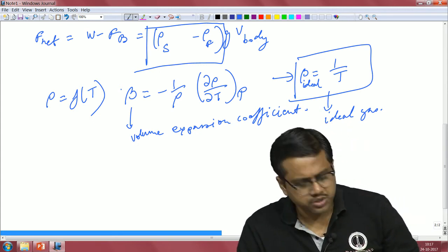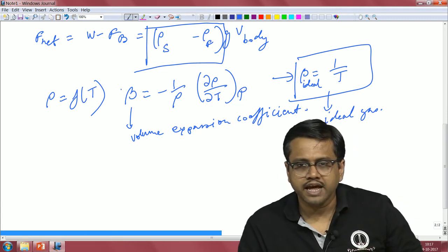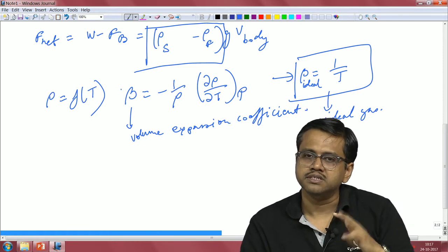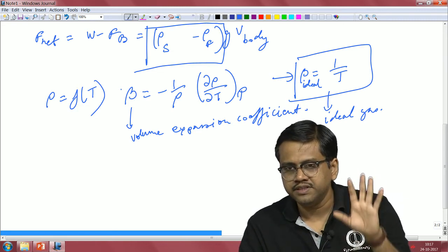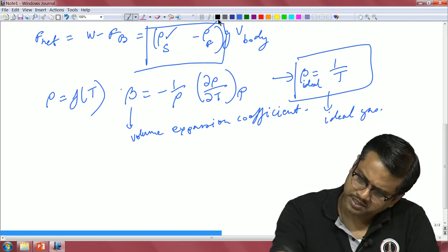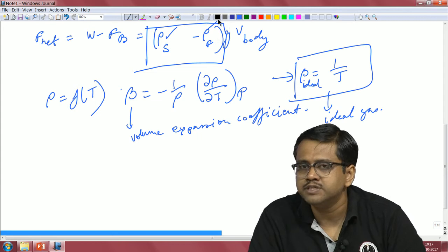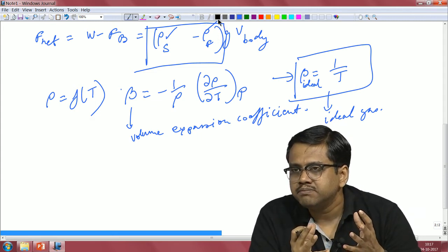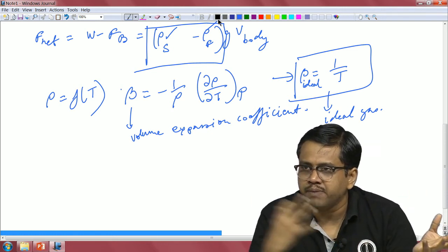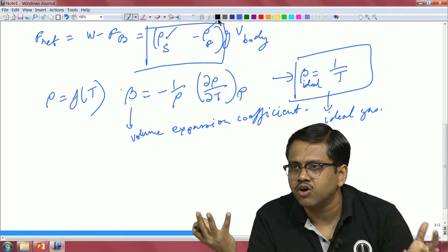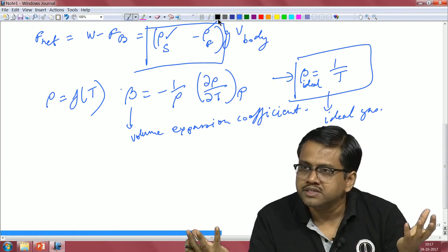Okay. So, now that we have established that there is something called natural convection, and natural convection does happen because of the change of density, we have already seen that the difference in density matters, as can be seen from the Archimedes principle. So, imagine in that particular case, instead of S and F, what we have is basically the same fluid, but at two different temperatures, correct. In the case of Archimedes principle, of course, it is the ship and the fluid, right. So, there is a very stark contrast in the density between a solid object and the fluid concerned.